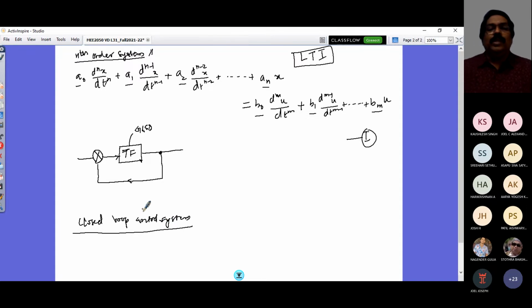So that is exactly what the popularly called double lane change test of your vehicle is. You are to overtake a vehicle, and you have to go in your track. So you give a steering input, and then again you correct the steering, and then you are overtaking and going. So this is from the control feedback from the response of your vehicle. And one of the closed loop tests is this double lane change test.